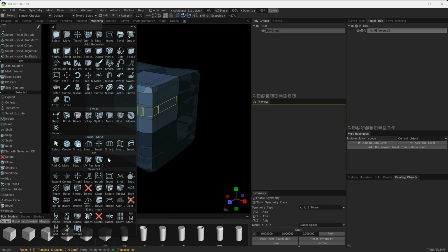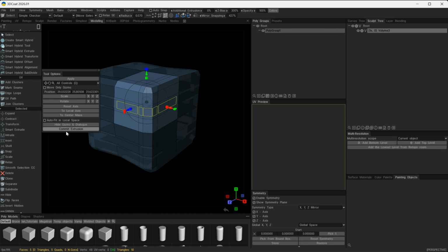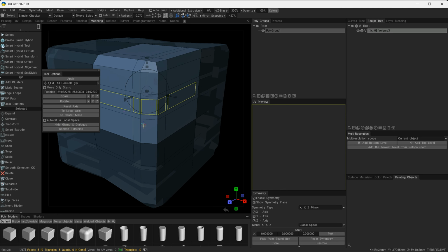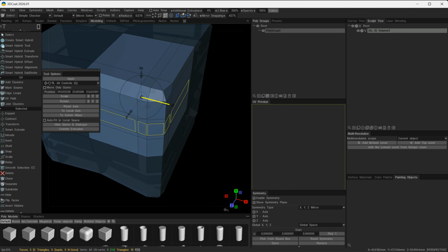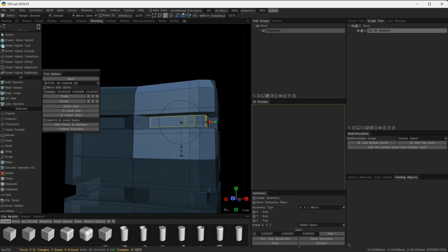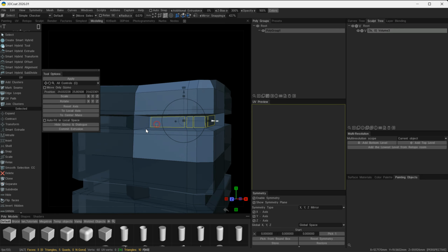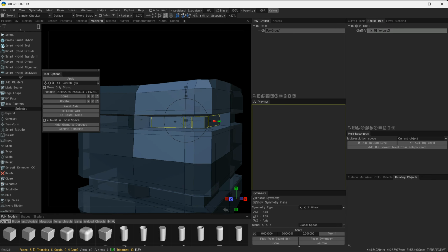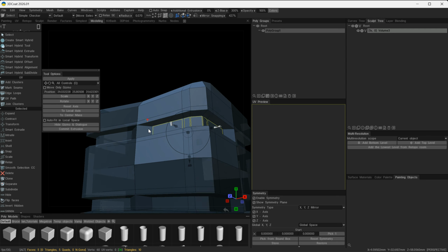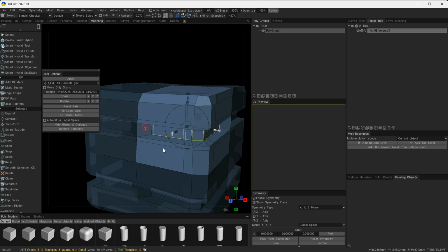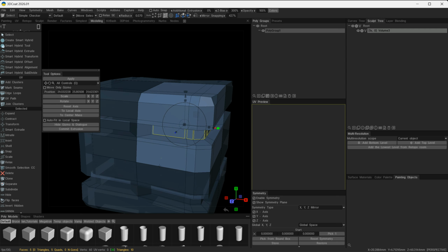So let's go back to my transform. Let's hit an extrusion on this one, and then let's shrink this down and pull that in. We can see here that we have this problem where it's just leaving those outer edges, and this extrusion here, these faces are snapping still to the center. So how do we correct that?